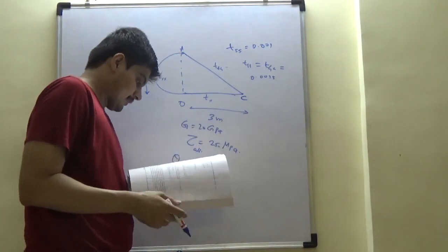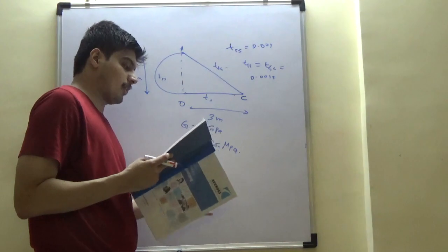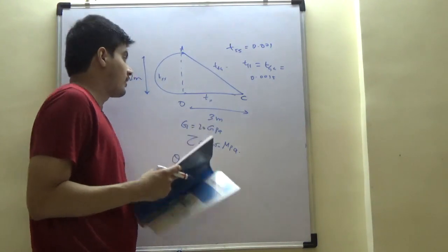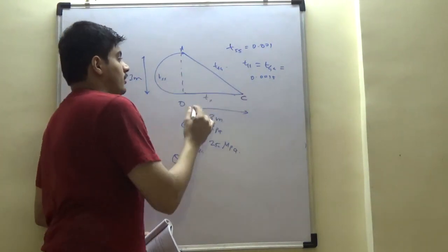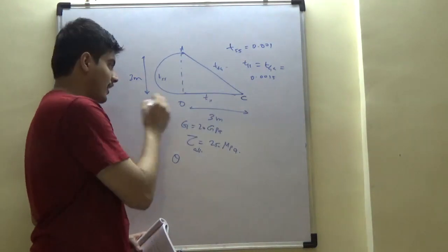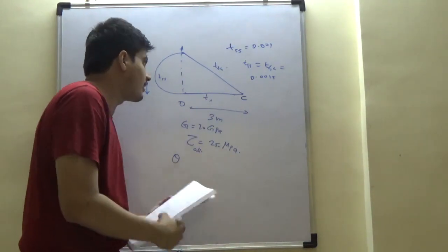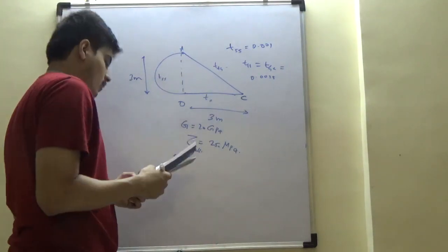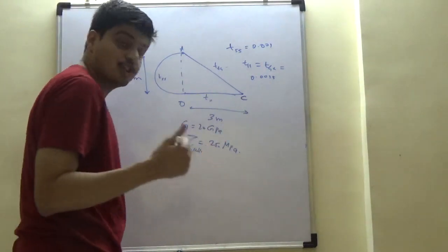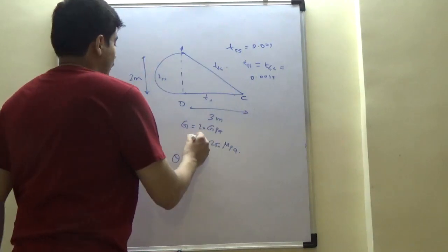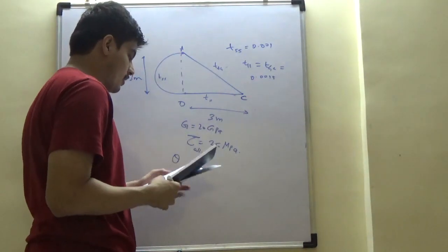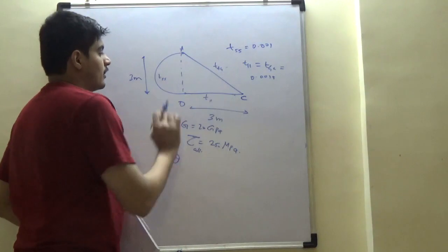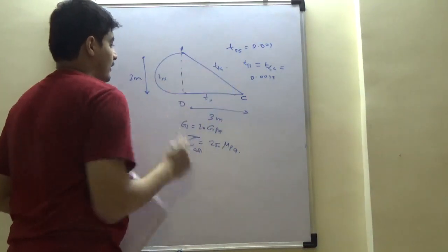This is an extremely important result, by the way. This is a cross section, the sectional view, right? Rather than becoming an ellipse or a circle, it is this open-ended section with these thicknesses. So we have to find the shear flows, and based on the shear flows we have to substitute these taus. First we have to find the area.